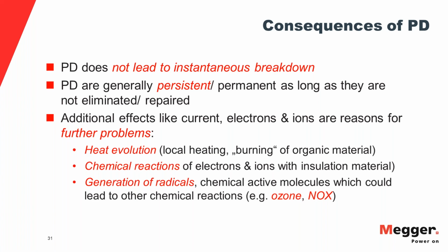And the consequence of that in the cable can be dramatic. You have heat evolution, as it's called, because of the heating in the insulation from the discharge. You have byproducts that are eroding the solids or even the PILC, or causing tracking in the PILC, and all the vaporization, the local vaporization of oil.